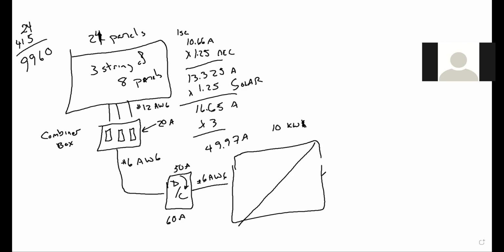Now we want to size the wire going out, the PV output circuit. Well, how do we do this? Bear in mind, this is a 240 volt AC. Up till now, it was DC. In fact, if I look, I could tell you that under standard test conditions, the VMP over here was 40.9 volts. That's VMP.